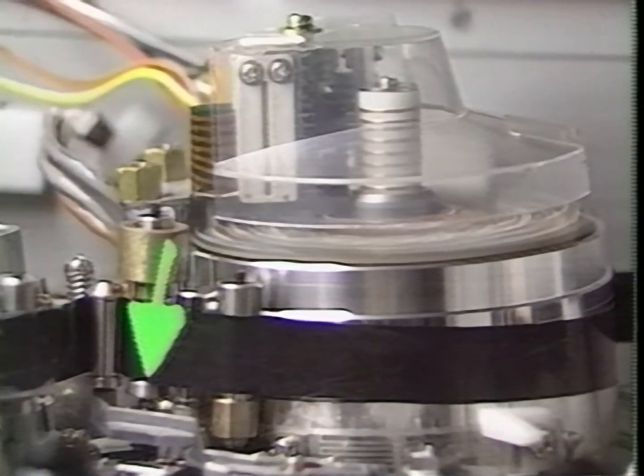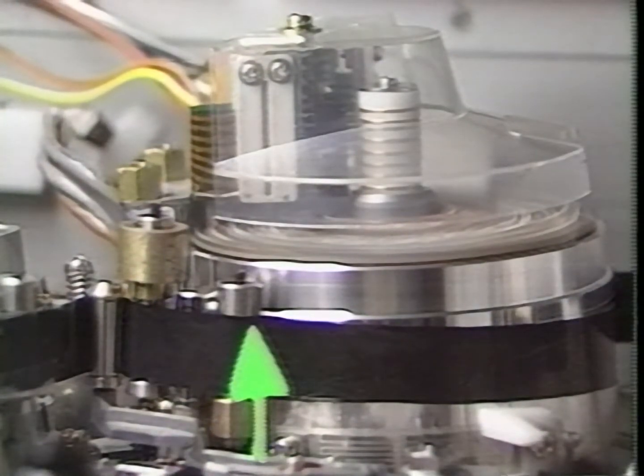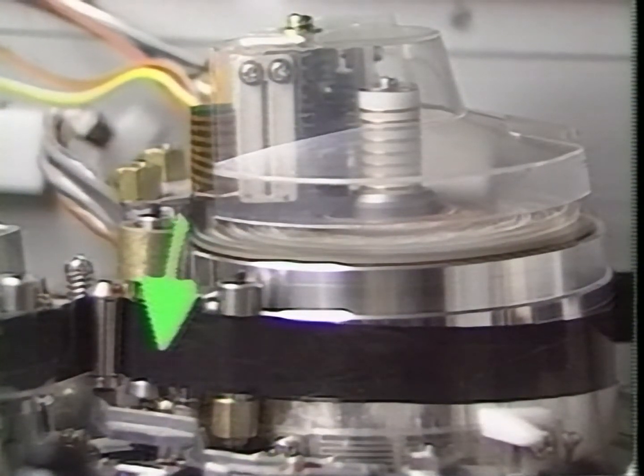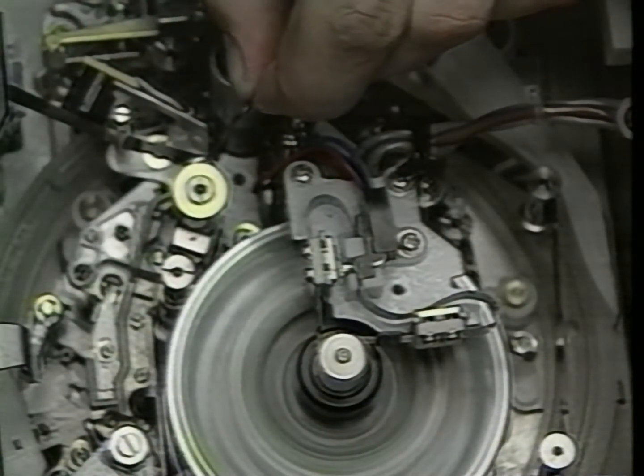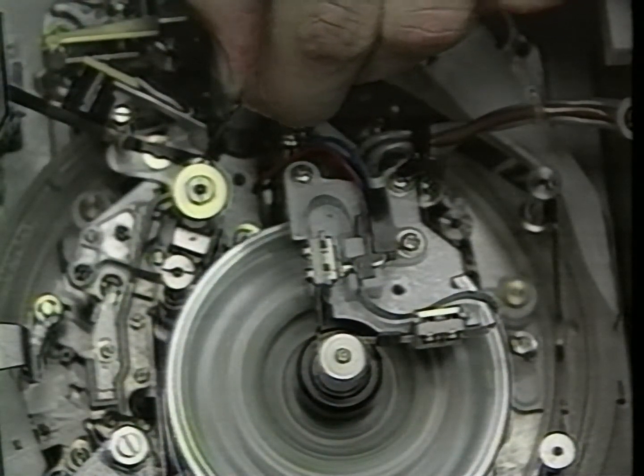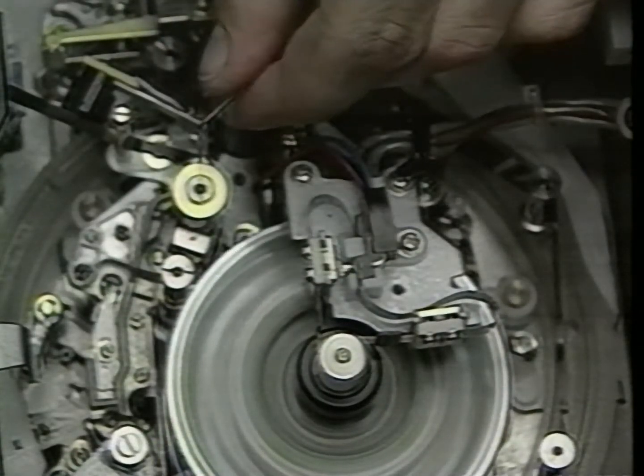Tape guide 1 is used to control the lower edge of tape. Since the tape path is now stable at the upper edge, tape guide 1 is adjusted so that it contacts the lower edge of tape without tape curl. Each guide should be locked in place by the set screw at the top of each guide.